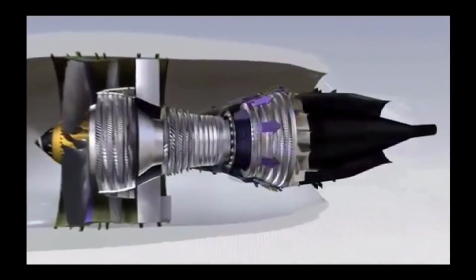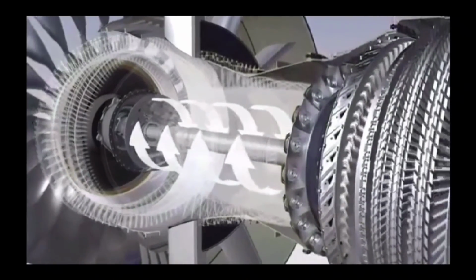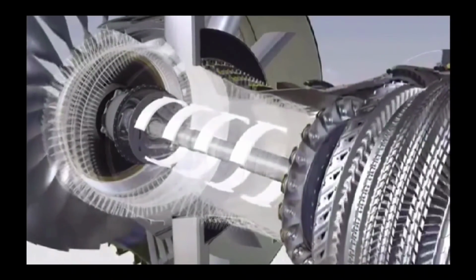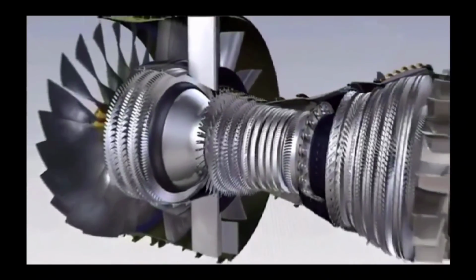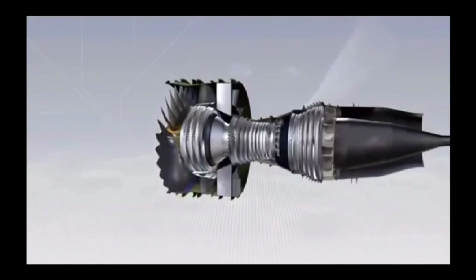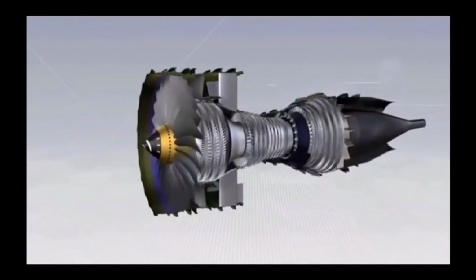The pressure of the air drops as it passes through the turbines and makes them spin, and the turbines, whose shafts ride within one another concentrically, in turn drive the fan and the 2 compressors. The air is then expelled through the primary duct, joining the air from the fan stream. A turbofan is therefore a flow cycle engine. Air is compressed, then heated by burning fuel, after which it passes through the turbines which drive the compressors and the fan.